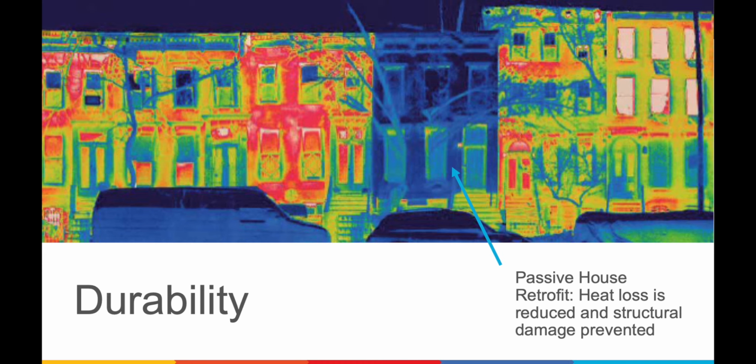The interesting thing is this, which is all blue, which means it's very cold. That's a passive house renovation. It was the same kind of code minimum, not so good house. They did some renovation, stuck some insulation on it, did the air tightness, and put in better windows. Now, if you look at the frame, it's that kind of green. The frame of a passive house is always your worst performing spot, and it is about the same color as some of the old walls. So windows are as good as old walls.